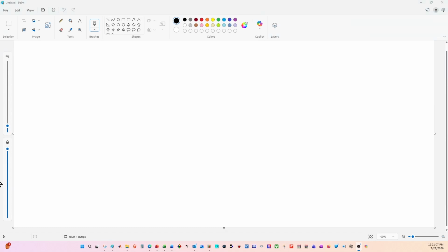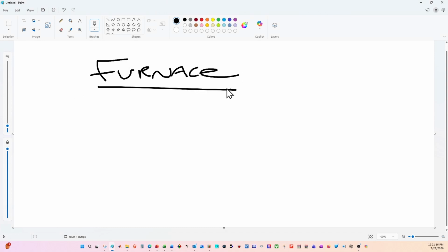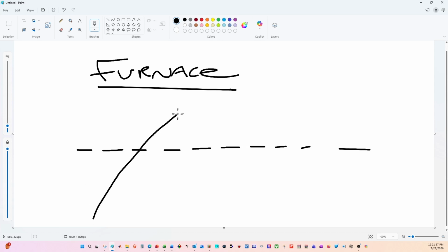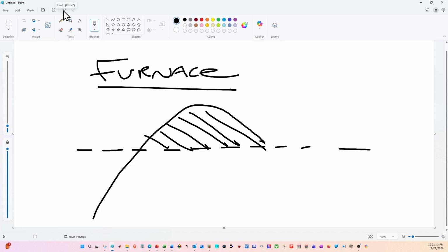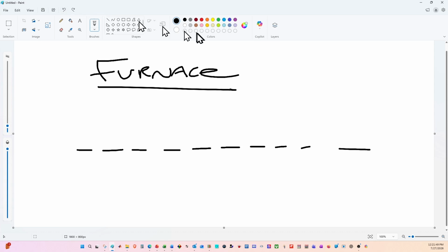Now, what would a practical example be? The one that I can think of is possibly a furnace. I've worked on processes where in the past we'd have to melt gold-bearing solutions or products down at at least 1063 degrees Celsius. In a case like that, you don't want to overheat your oven, because if you took the process variable too far past the set point, you could damage the bricks on the inside of the furnace itself, and you might have to replace those bricks in a very short period of time.